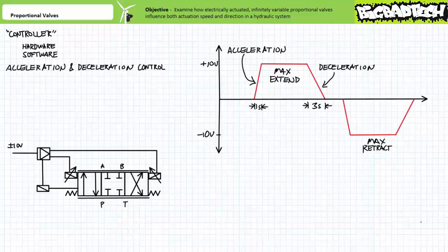It's extremely hard to nail down what a proportional valve controller is, because it might be some independent physical object you can hold in your hand, or it might be some nebulous invisible entity you program, and is most likely a bit of both. Case in point being our earlier discussion on hysteresis. Closed loop control of the spool position may already be integrated into the proportional valve, making the proportional valve itself part of the proportional valve controller. Another example being a PC running manufacturer-specific proprietary software used to program a proportional valve. When the program is stored in the proportional valve's non-volatile, meaning semi-permanent, memory, it's disconnected.